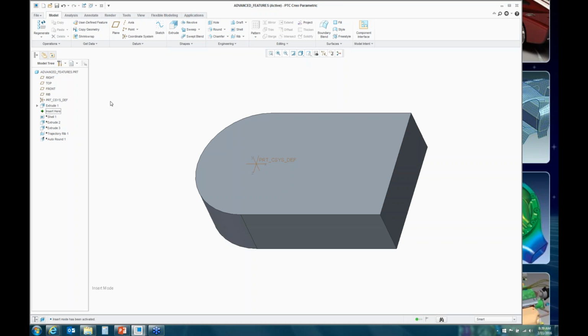So to select a seed surface selection, what we have to do first is select a feature, and then if we move our cursor slightly, the next surface highlights. We'll select that surface. That is now my seed surface. And then holding down the Shift key, I'm going to select one edge of that seed surface to identify the loop of surfaces that I want to collect.